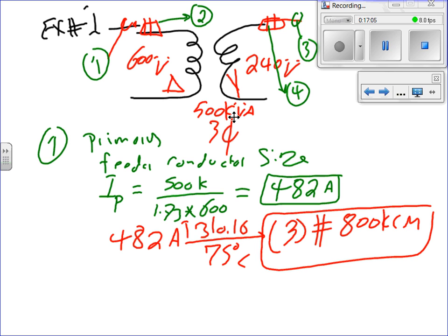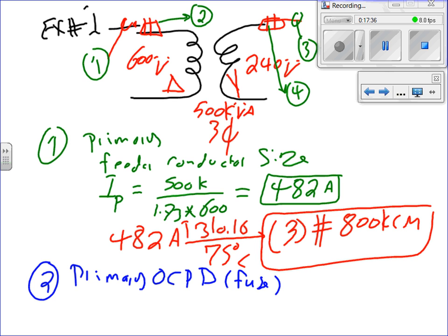The second thing that we need to, any questions? Bill, my friend, Camille, and Jem, and Urbab? No? Okay, so number 2, we need the overcurrent protection device for the primary. So that's called the primary overcurrent protection device. Fancy name for a fuse or circuit breaker. In our case, it's a fuse. In my case, it's a Mr. Fuse.